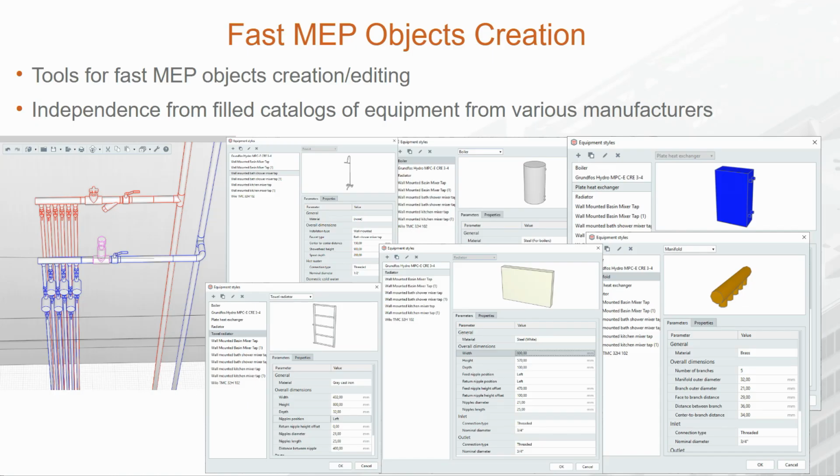The second option is to apply basic programming skills and use a domain-specific language to create complex equipment. This enables you to develop BIM catalogs in accordance with your company's internal standards. Any created equipment is automatically connected to the engineering systems using the automatic tracing tool. This tool automates MEP system tracing in accordance with the geometry of rooms. Watch how this tool works.